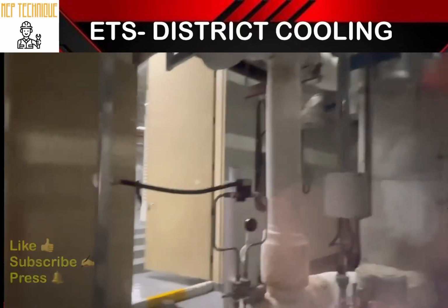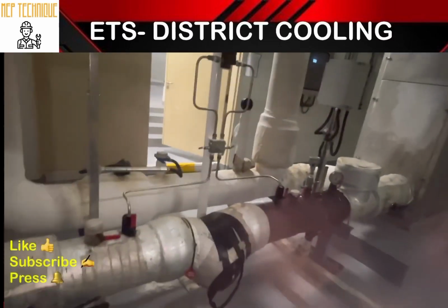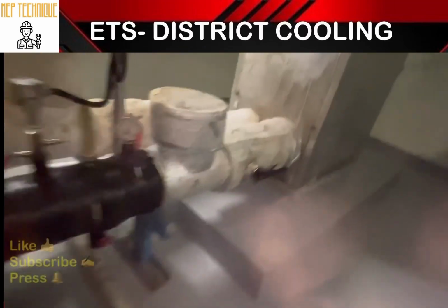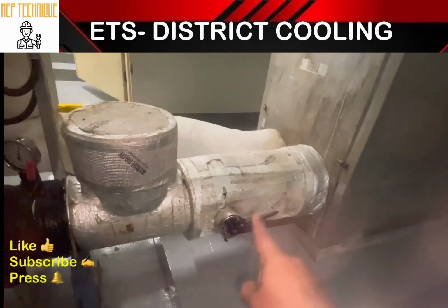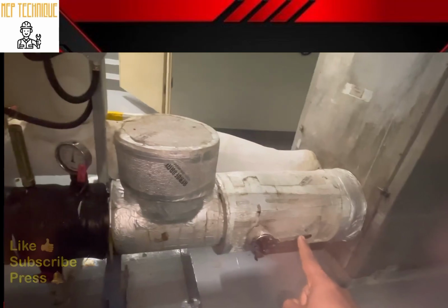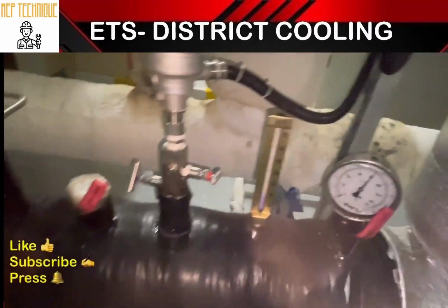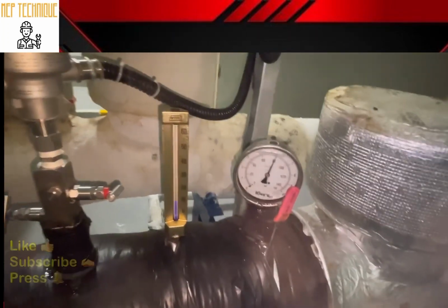This is the bypass in the chilled water secondary line. This is the butterfly valve. With the butterfly valve you can isolate and regulate your chilled water supply. After that, this is the pressure gauge, and you will get to know the pressure of the chilled water line.